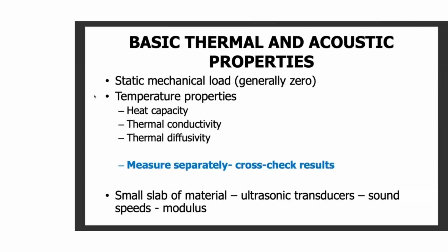We can also take small slabs of material using ultrasonic transducers, and we can measure the sound speeds and estimate, with knowledge of the density of the material, a modulus of it. So these are some general measurements you would make before going near a high rate facility.